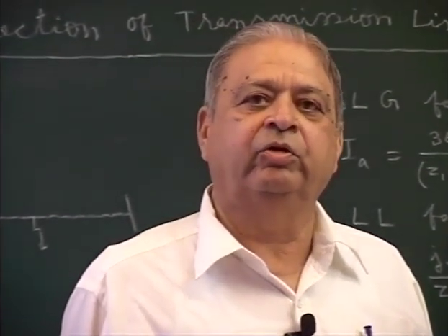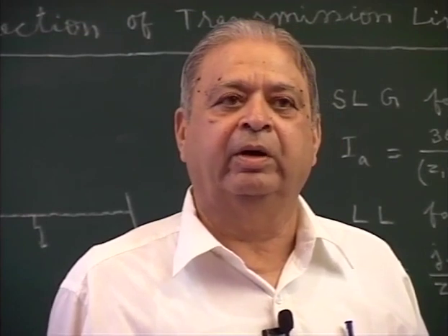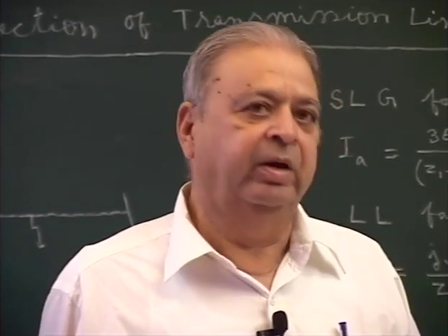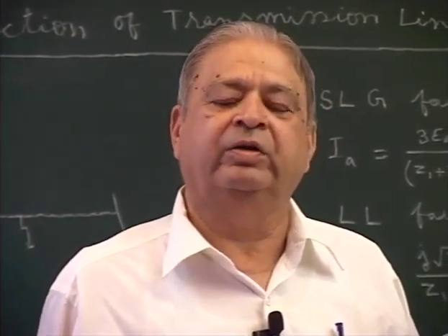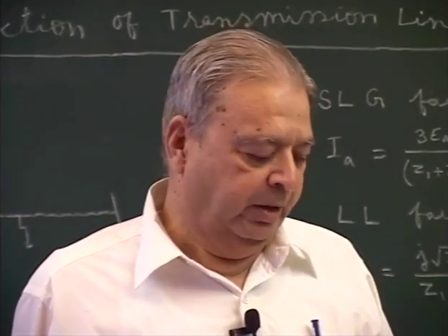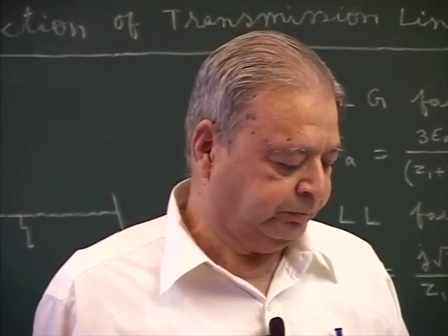Z0, that is the zero sequence impedance, does not appear anywhere in the expression, and the value of fault current for the same location of fault is different.